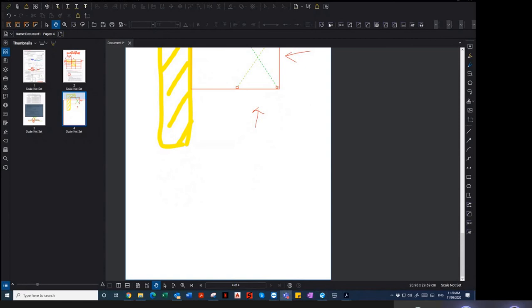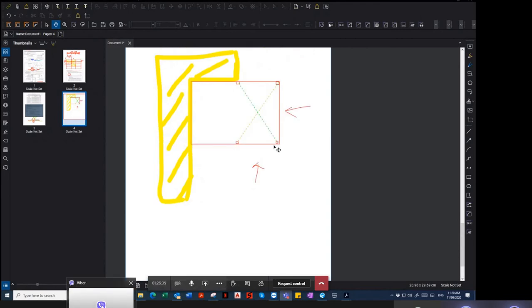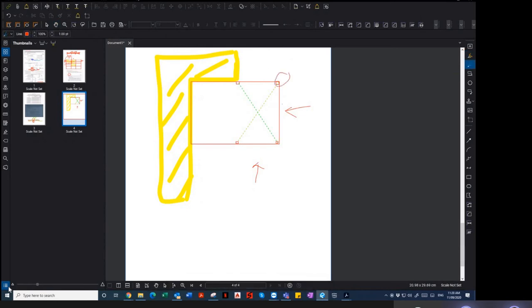So we've got wind, and our most critical post in here is that particular post and this particular post, in that direction. If the architects have only given us a 90 by 90 post, it doesn't work for deflection in this case. Even if it's 3 meters from there to there, you would tend to struggle.